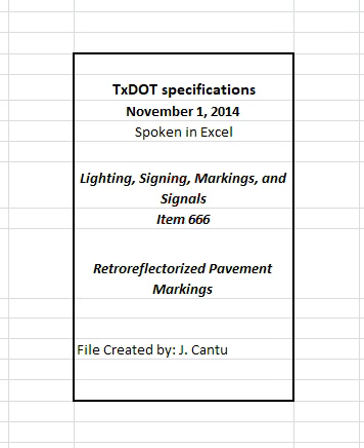Use material for guides that will not leave a permanent mark on the roadway. Apply markings on pavement that is completely dry and passes the following tests. Type 1 marking application. Place a sample of Type 1 marking material on a piece of tar paper placed on the pavement. Allow the material to cool to ambient temperature, and then inspect the underside of the tar paper in contact with the pavement. Pavement will be considered dry if there is no condensation on the tar paper.